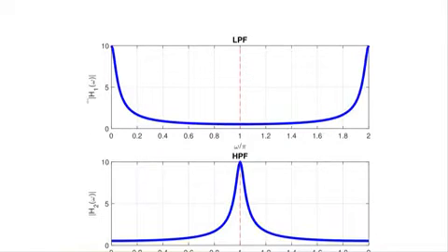For the first system, we notice that it's a low pass filter. You see here, the high frequency is pi. Here the plot is omega over pi. 1 means pi, and 2 pi is equal to fs. Here is fs over 2. Anyhow, lower frequencies can pass, but there is considerable attenuation for higher frequencies.